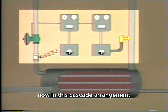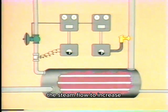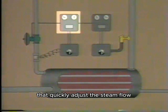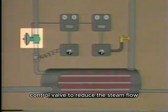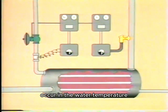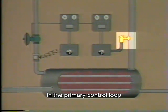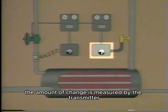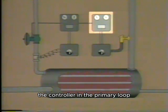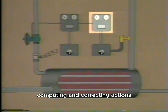Now, in this cascade arrangement, when there is a disturbance that causes the steam flow to increase, the steam flow sensor triggers a control signal that quickly adjusts the steam flow control valve to reduce the steam flow. Whatever change does occur in the water temperature is sensed by the water temperature sensor in the primary control loop. The amount of change is measured by the transmitter and converted to a signal to the controller. The controller in the primary loop performs its normal measuring, comparing, computing, and correcting actions.